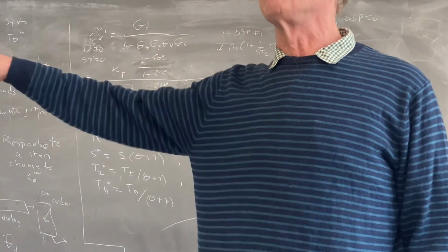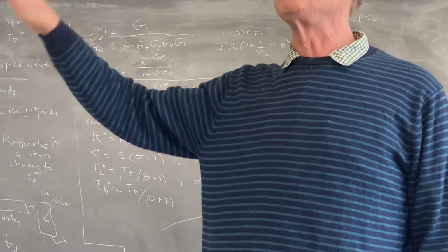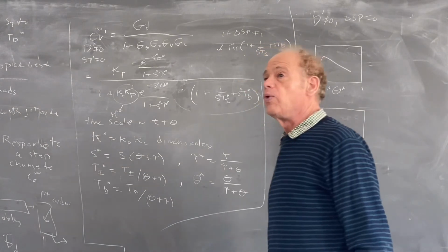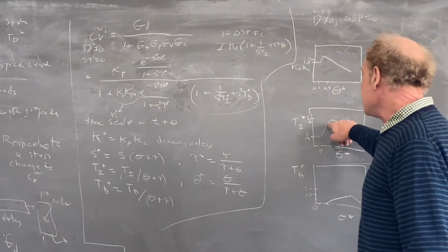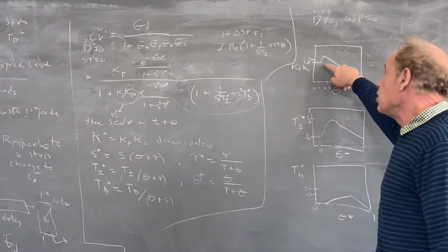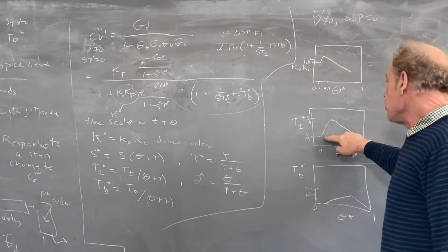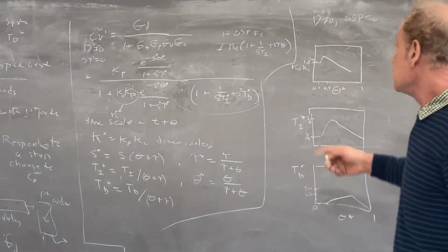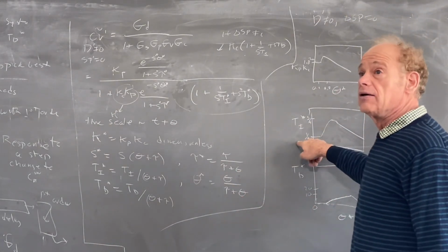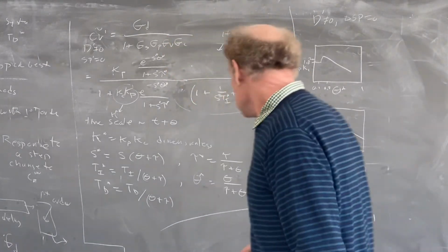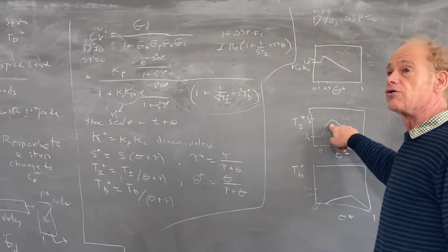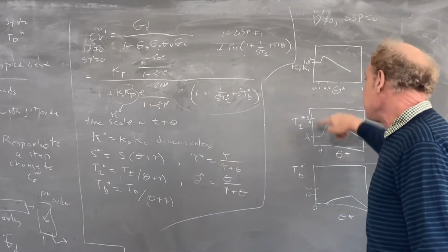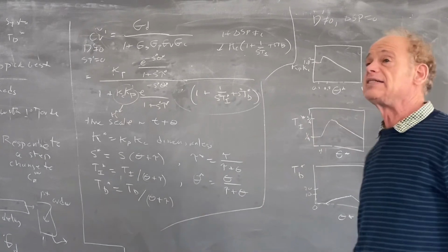So it just takes care of the long time. It says short time, we'll leave it to the proportional controller. But at long times, we'll take over. And notice we're not detuning it that much because it's multiplied by KC. So by this going up, we're keeping the integral controller working because it's KC over TI. That's the strength of the integral controller. So this going up doesn't mean we're turning off the integral controller. It means we're just trying to keep it still working because KC went up, so we have to raise TI.